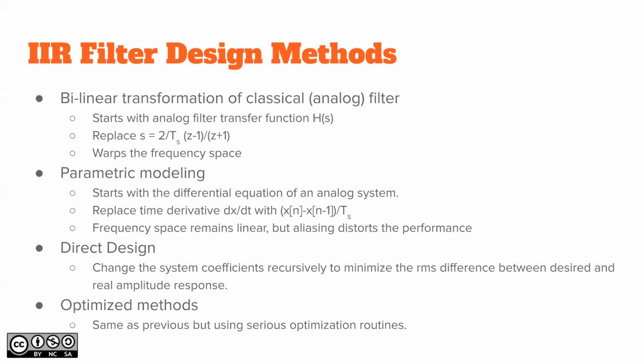Now this is actually a simple method. It does not have the aliasing effect as we had with that funny FIR impulse response truncation kind of thing, but it warps the frequency space, since on analog systems the frequency axis on the S plane goes from minus infinity to infinity on the j axis.